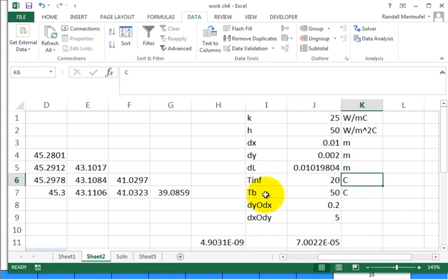And what I also did to make the cells a little easier is I named them. Currently, the cell that I click right here is D2. D for the column, 2 down for the row. If I come over here and click right there, it's J1, but I've renamed it to be K underscore. So I have a name for it. Anytime I want to use it in a formula, I can just type it.